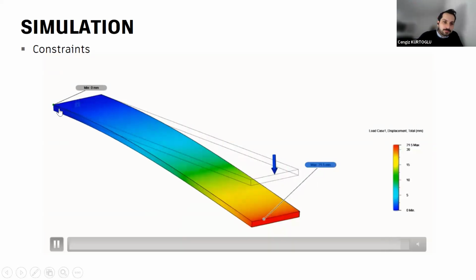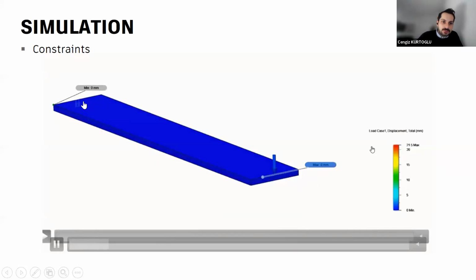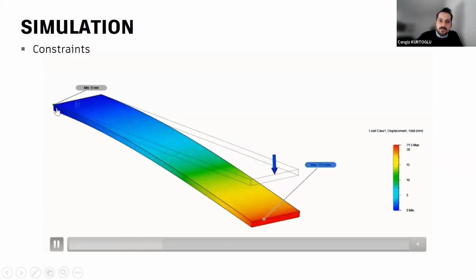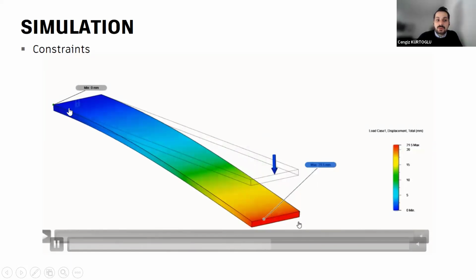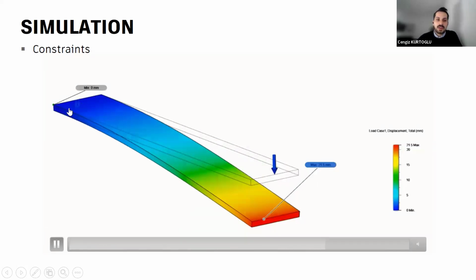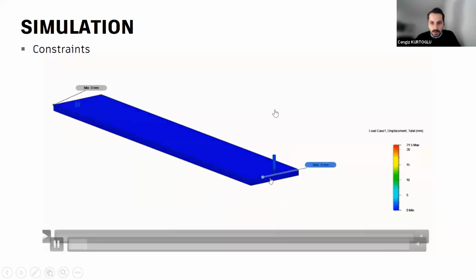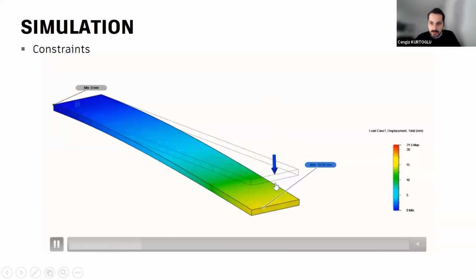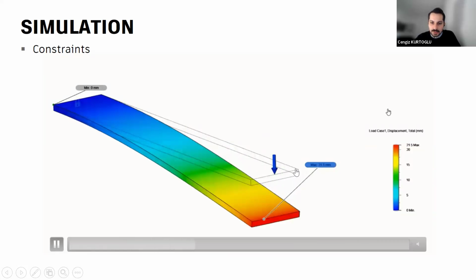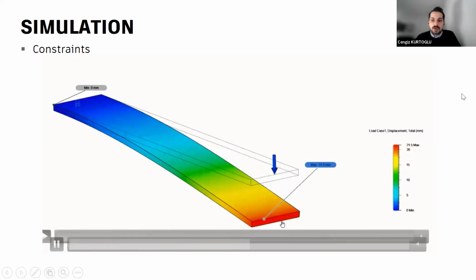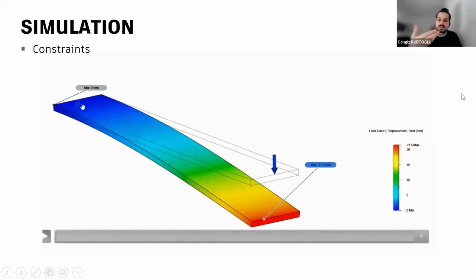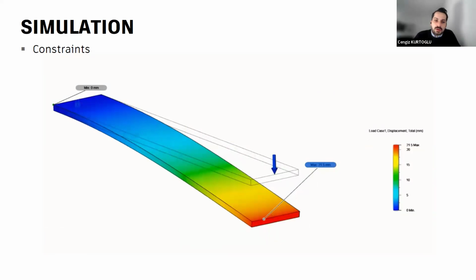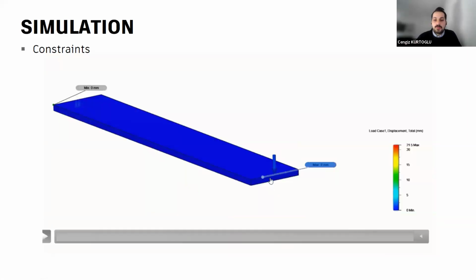As you can see, the end of the rod, this face, is assigned as a constraint fixed in the x, y, z axes, and then there is a load here on the edge of the part. After this solution, it depends on the materials. You can change the materials, and the results will be different.